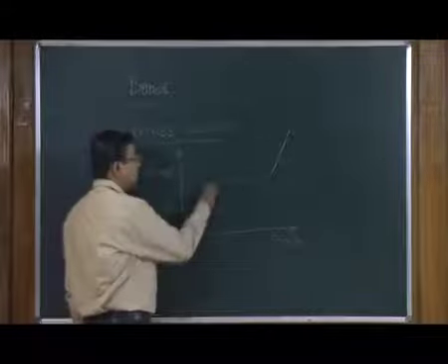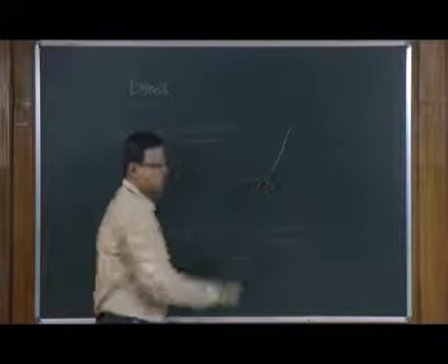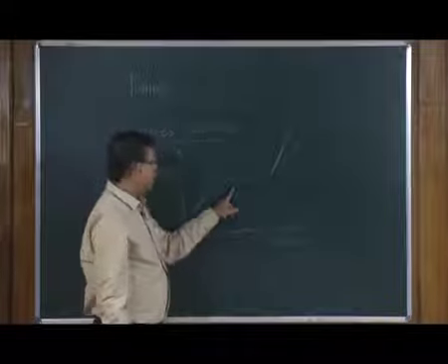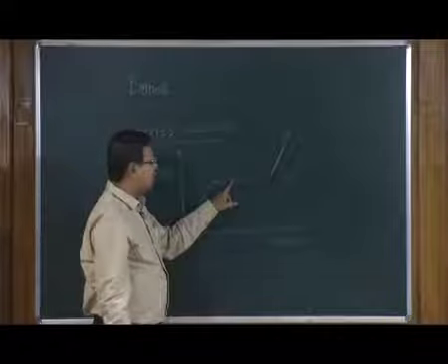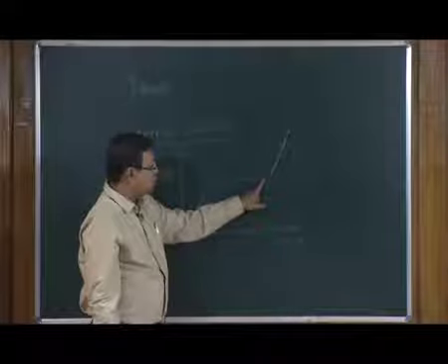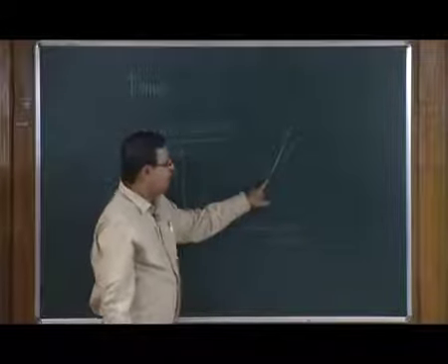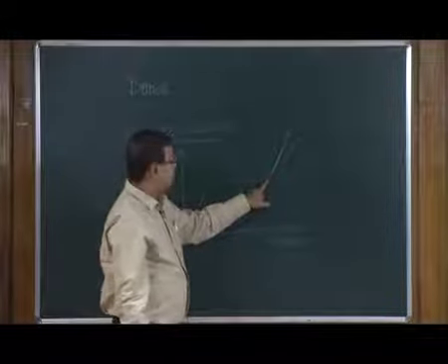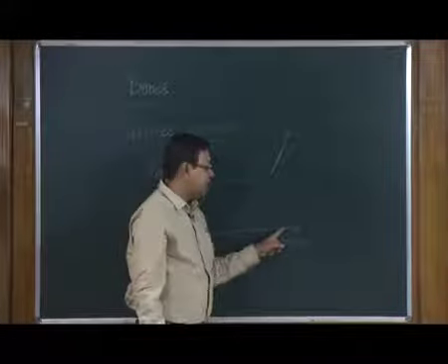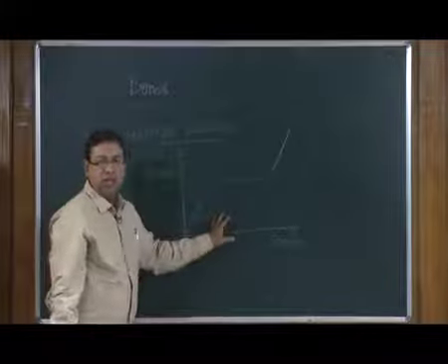This part is somewhat known to us up till this, and then of course, it becomes flat for quite a while. That is, there is no application of stress. However, the strain keeps changing, and suddenly after a certain point the stress becomes large without significant increase in strain, and this is very different than what we have learned so far.